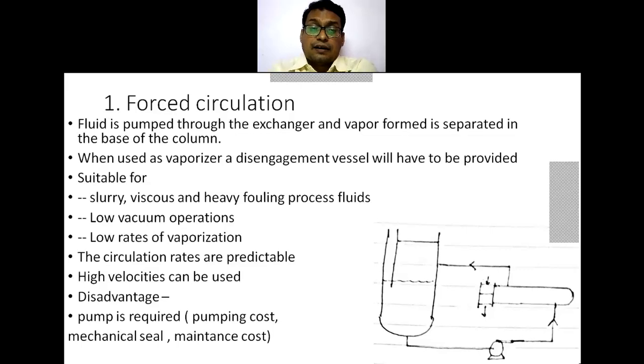But when the pump is there, you are putting in an external source of energy. Cost of pump, the pressure drop will be more, maintenance cost will be more, and for the pumps which are operated at a higher temperature, because this is at the bottom of a distillation column, the temperatures are high, and as a result, for a better leak proof pump, you will require mechanical seals, and these mechanical seals which prevent the leakages of the pump are very costly.